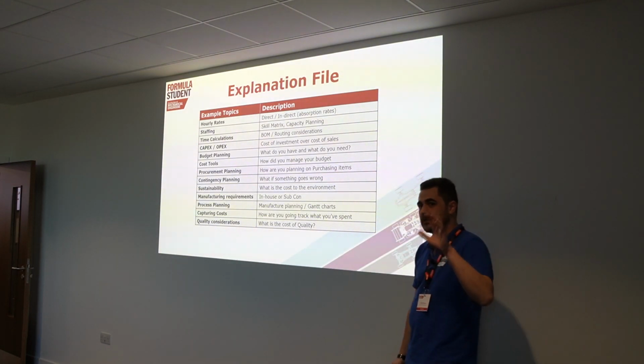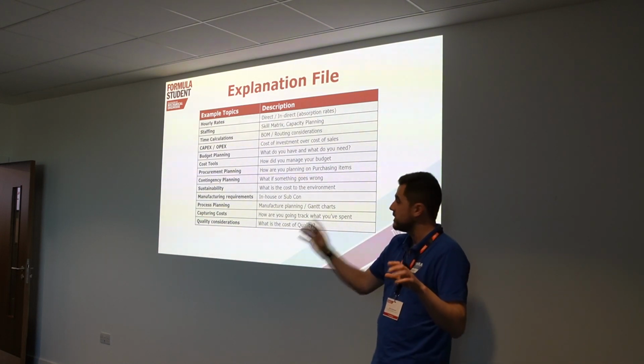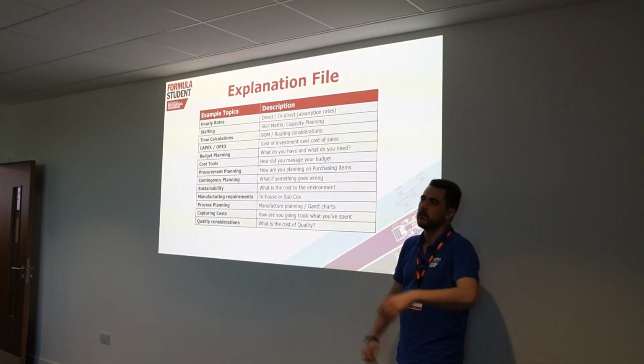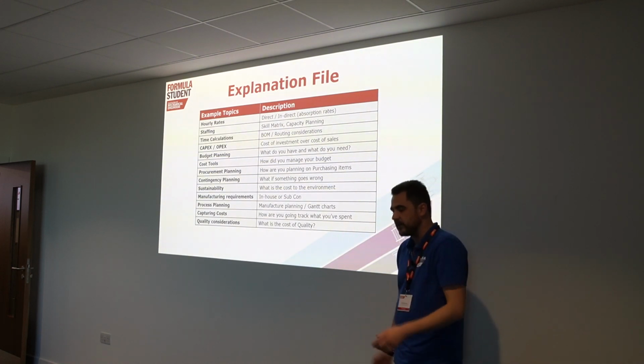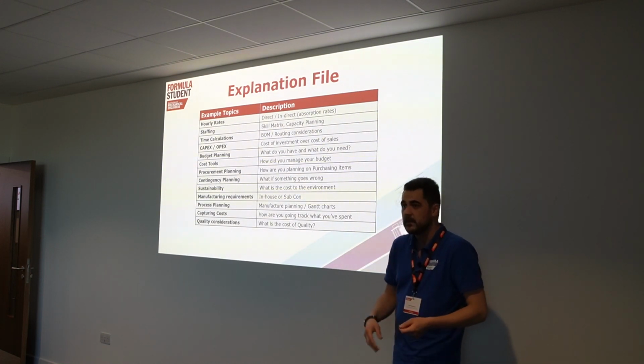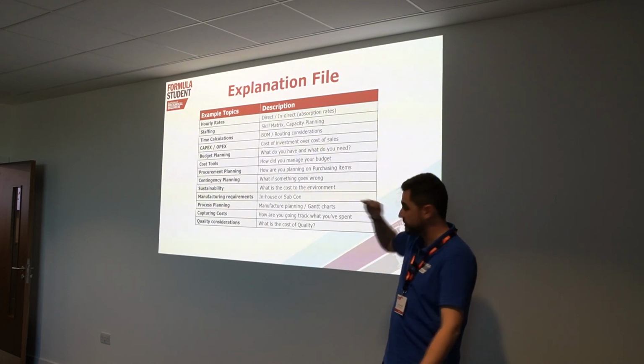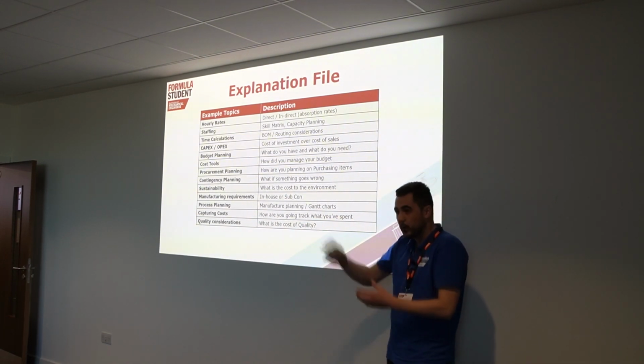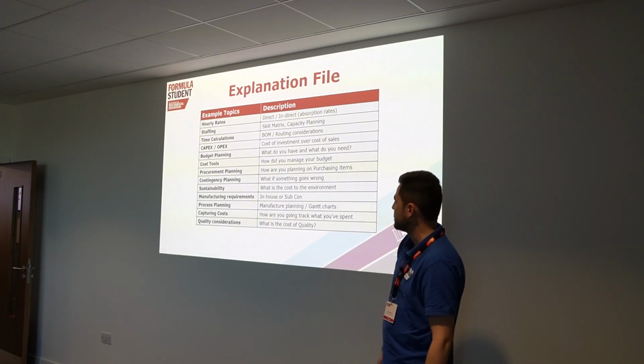So as I said earlier, most things are broken down into bill of materials and routing. This is where your routings come into effect. If you're going to kit cut, it's unlikely you're all on a Zund kit cutting for composites, but if you're going to hand trim them, tell me how long that took. I need to know that it's been kit cut, it's been laminated, has it got a debulk, how does it look? Break it down into real small bits.